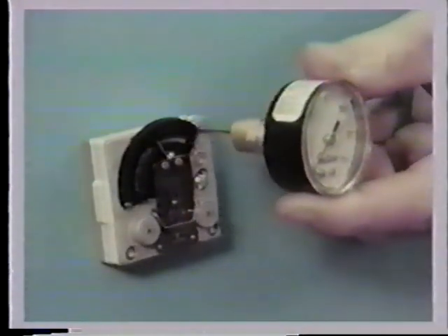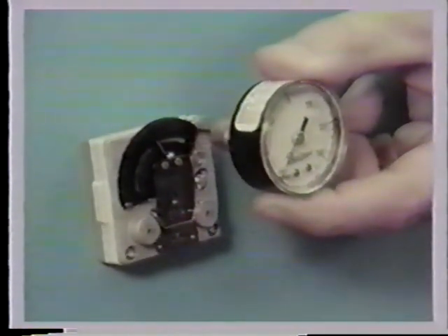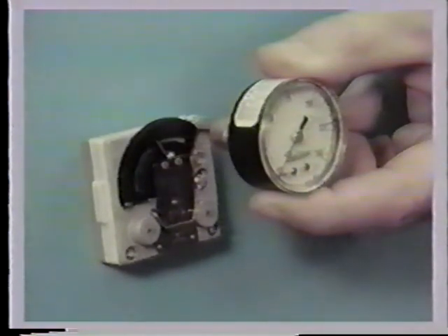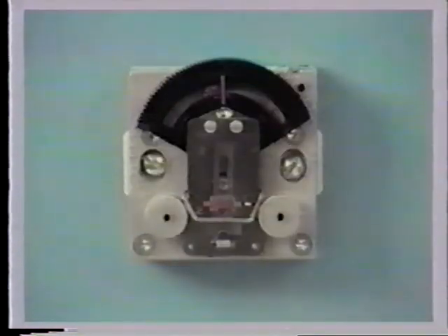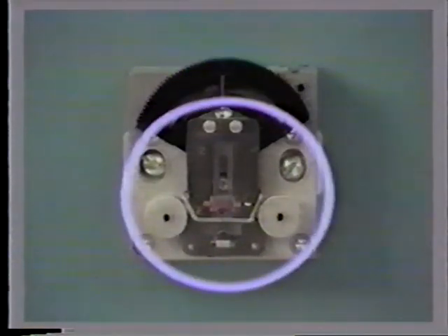On the thermostat body is a branch pressure tap, which is used with a gauge and branch tap adapter to read branch line pressure for thermostat calibration. The bimetal assembly on the thermostat senses ambient temperature changes and responds by producing changes in the branch output pressure. This bimetal assembly is very heat sensitive. Touching or even breathing on the assembly will produce a rapid change in branch line pressure and inaccurate readings. Be careful when attempting calibration of these devices.